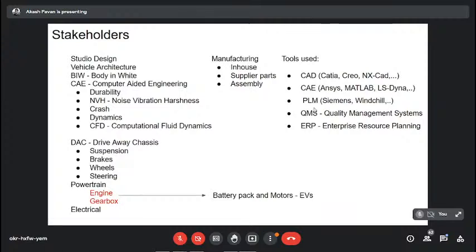So we have durability analysis. Those in production and mechanical might relate to it. In durability analysis, we get to do the fatigue analysis of the parts. Fatigue in the sense of cyclic loading and reloading of the parts, and then we do the noise vibration harshness test. So NVH, in NVH we test. NVH is very important in designing the parts.